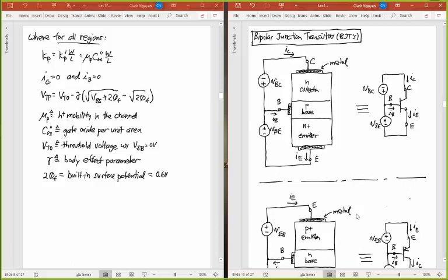There were all sorts of issues with technology. There were too many non-idealities in creating oxides over silicon, too many interface states and contaminants that didn't allow us to make NMOS and PMOS transistors very easily at first. But we did learn how to make bipolar transistors, an alternative way to create a transistor. So that's why bipolar transistors came first.